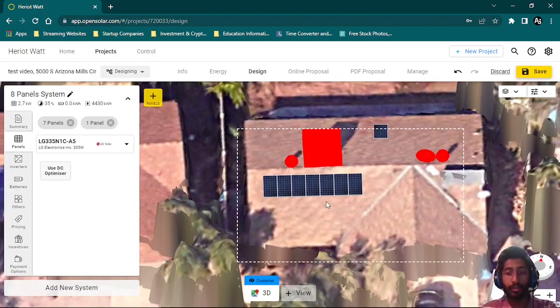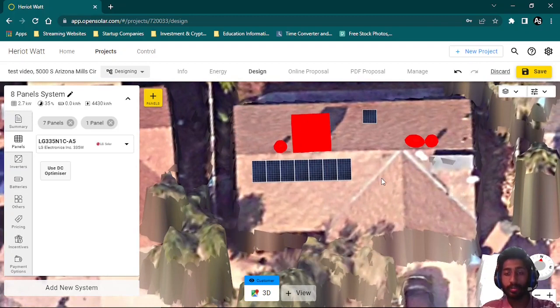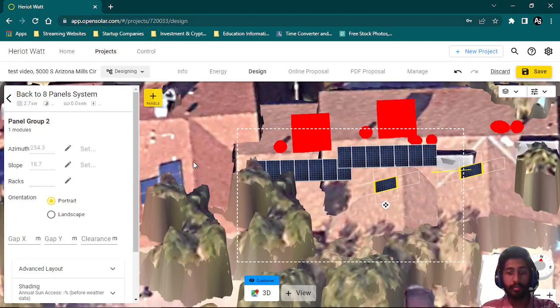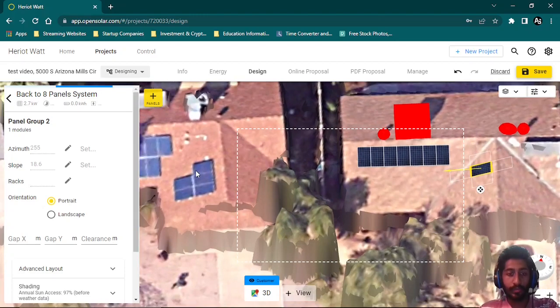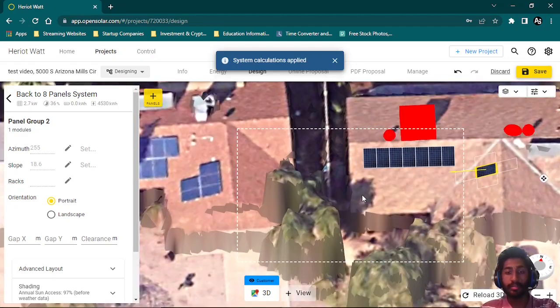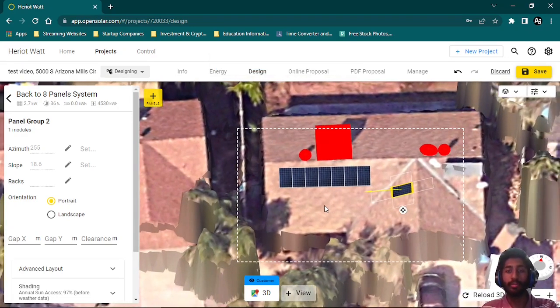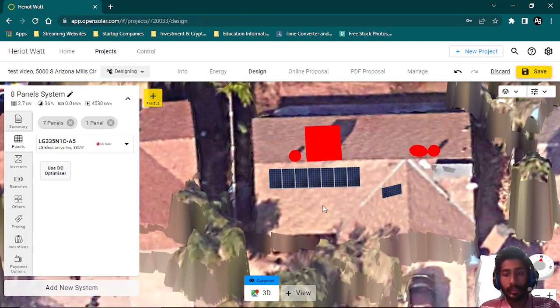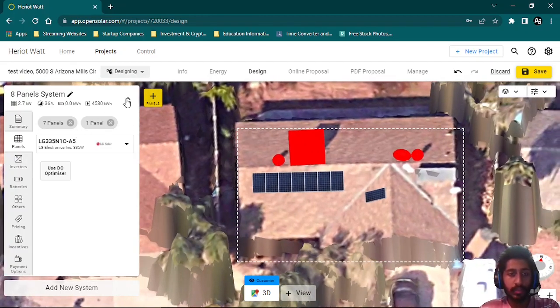You can also install them east as well. So if I were to move it around and install it due east, as you can see here, facing that side due east. If you want to look at an example of how the other house has solar panels installed, you can see it's also due south and also east. This is the type of arrangement you want to install. For example, in my country, Pakistan, which is in the northern hemisphere, you would install solar panels due south, facing south. And that's pretty much it, not too hard. The general rule of thumb.